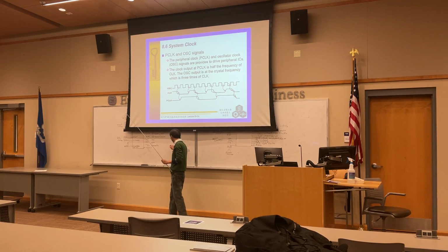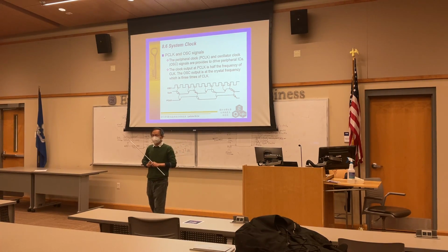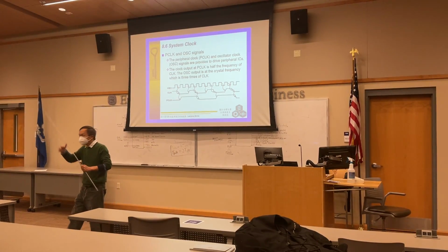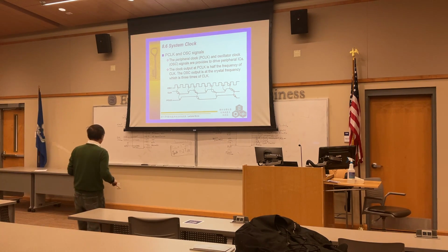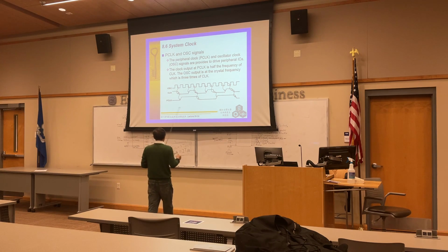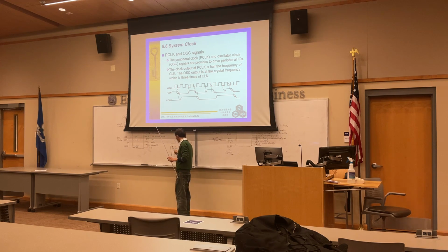That's the typical relationship, because every time you do a conversion, you slow down a little. So if we tell you what clock we need for your peripheral, you can trace back to your T clock and oscillation clock. That's a typical relationship.